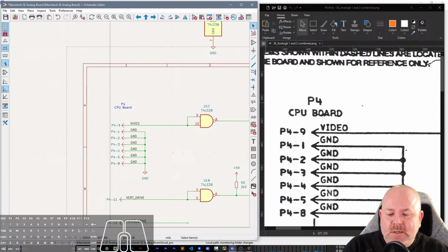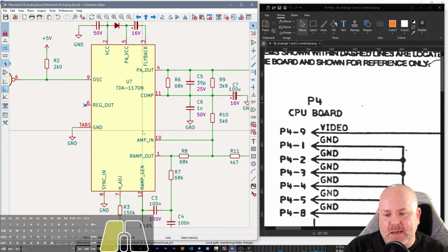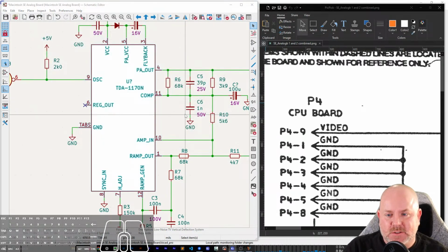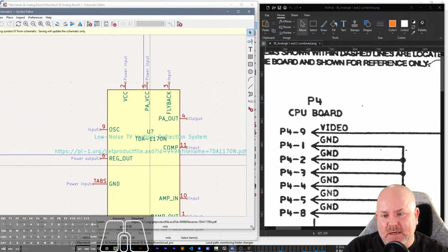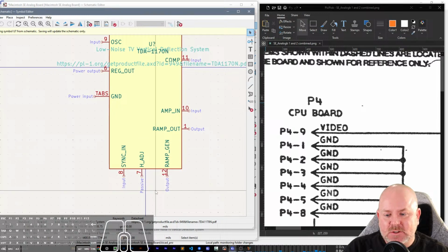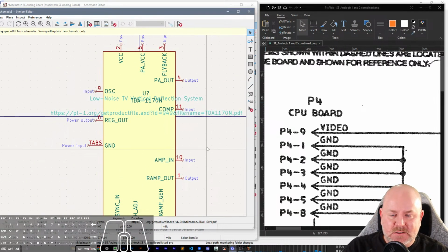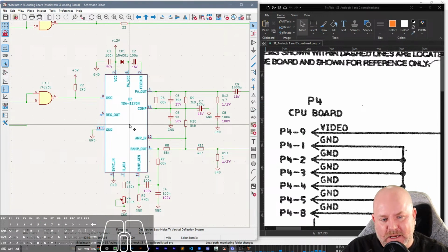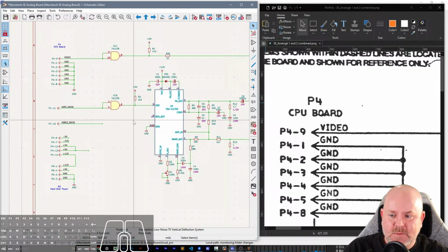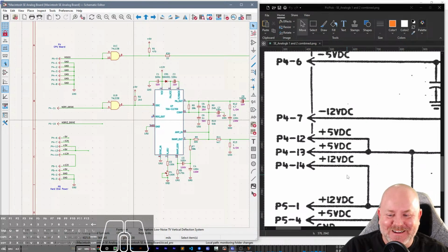And so this symbol I created, these are set to passive because they are technically a connector, and connectors should be set to passive. But in this symbol for the deflection controller that we created, if we go look at its definition, I use the data sheet to make sure we set, at a minimum, the power and the inputs and outputs. If there's pins that I'm not entirely sure how to handle, I'll make them passive or undefined. But for ICs, I try to set the pins correctly. So long answer to that question. Yes and no. Yes, no, and sometimes.